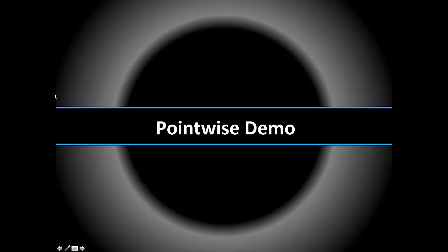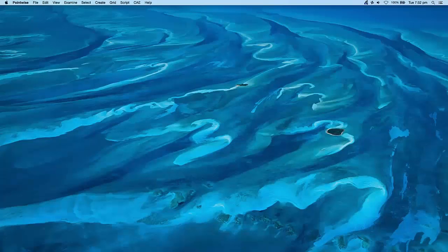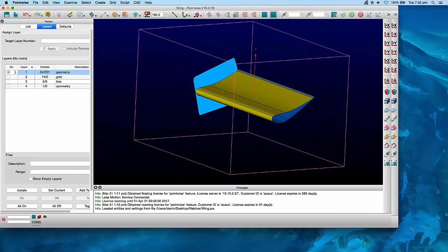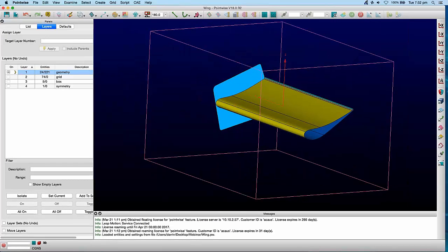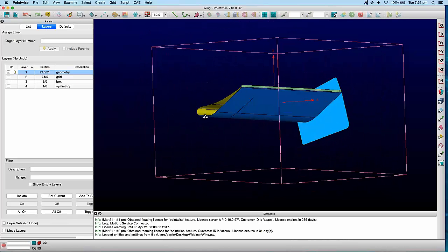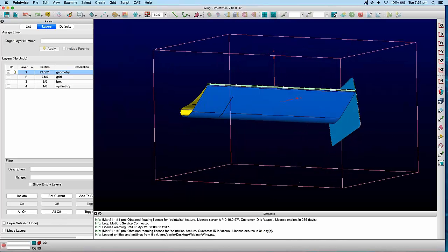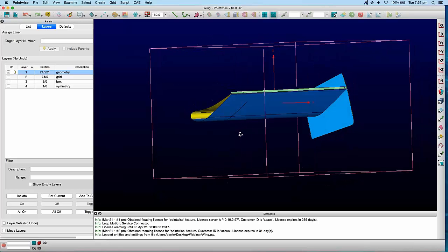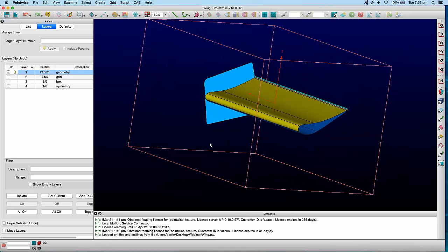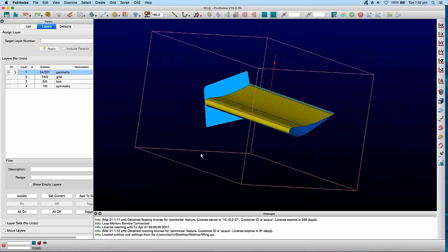Okay, so Scott's just talked about parts of the car. I'm now going to pull up some of those in Pointwise and go through a bit of a demo talking about the different meshing aspects and what's important there. So what we'll start with on this one is we've actually got half of the rear wing. This is the one off the VE, so you can actually see the piece in the middle there is where the centre mounts would be. So this is not an end plate mounted rear wing. And the box you see around that was just a region I put so I could actually generate a volume mesh on the laptop for the webinar.